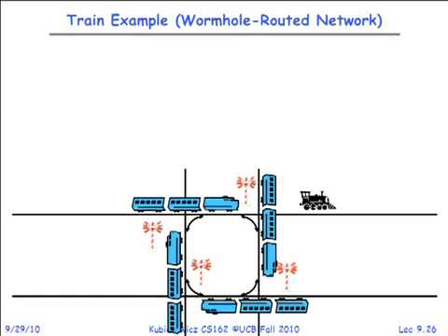And notice what we've got here. In a wormhole-routed network, packets actually look like trains. There's a head of the packet, and there's a bunch of flits in the packet. And you actually open up a path as the message is traveling, and you close the path behind the caboose or whatever. And while the packets are using up the network, they're actually taking space just like a train on a track. So this is actually a pretty physical scenario for a network.